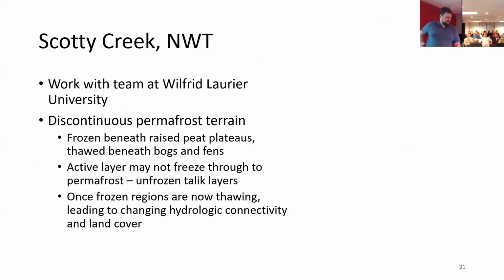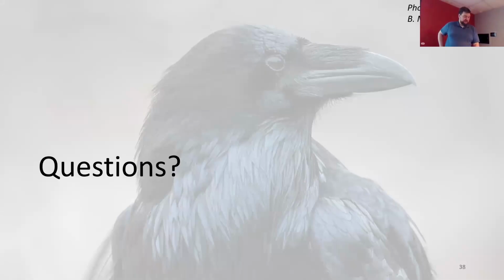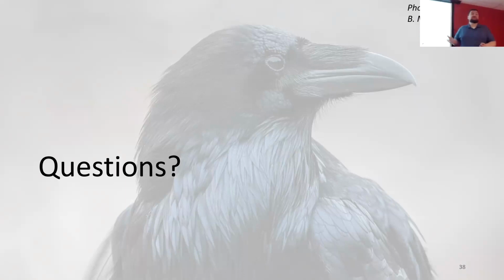Yeah, actually I thought I had a slide in there. I just skipped over it completely, didn't I? Oh yeah, I neglected to include my stream slide. So Raven also supports stream temperature simulation. It does a full thermal energy budget, mostly for stream temperature. It does land surface fluxes too, though I'd say it won't do it as capably as a land surface scheme, but for getting stream temperature and lake temperatures and incidents of freezing, it supports that. Now that's a lot harder to model than water flow because it's a lot more sensitive to local variations in stream flow, channel characteristics, incoming radiation, shading, and all those other things.